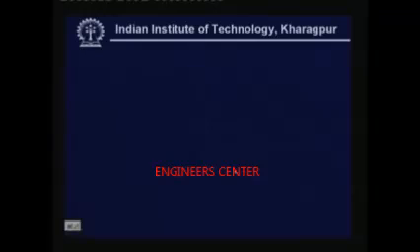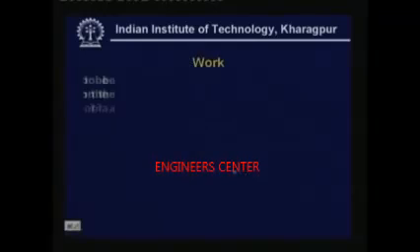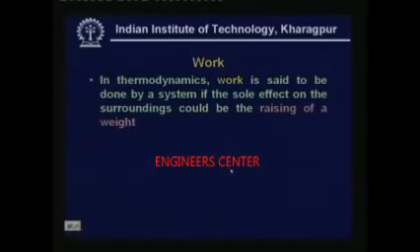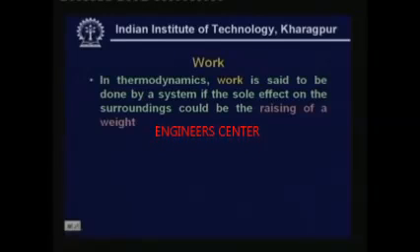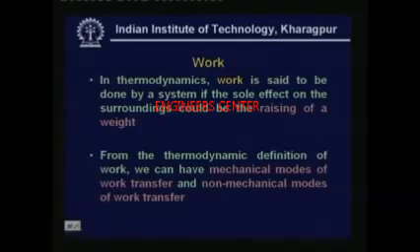Now, let us define work. In thermodynamics, work is said to be done by a system if the sole effect on the surroundings could be the raising of a weight. One thing you must notice here is that a weight need not actually be raised, but the sole effect could be the raising of a weight. This is the thermodynamic definition of work, and you can have mechanical modes and non-mechanical modes of work transfer.